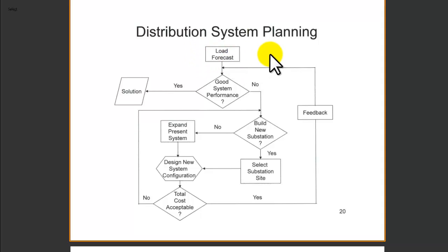The forecast is another challenging part, because we don't have a metering point at every part of the network. So sometimes the planning engineer has to selectively pick out the location or load type, do a thorough statistical analysis to find out where, and then based on the best knowledge, find out the information. I will talk a little bit about that in the next chapter of this book, because this is what we do in terms of predicting how much the power loss will be, and then determining the voltage profile for a particular feeder depending on the shape that we want.